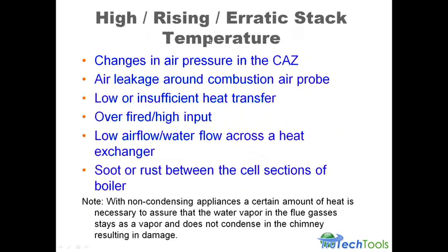Rising or erratic stack temperatures. All right, and stack temperatures, believe it or not, sometimes you'll pick up problems with stack temperatures before you pick them up with the O2 sensor, because the thermocouple is extremely sensitive. When the flue gases start to back up in the heat exchanger or get drawn back in because the combustion air zone is depressurizing, it's going to start to cool down those flue gases, and the stack temperature will start to drop. And if the stack temperature is going up and down, changing by like 10, 15 degrees, you probably have something going on with the pressures in that combustion air zone. Take a close look for that.